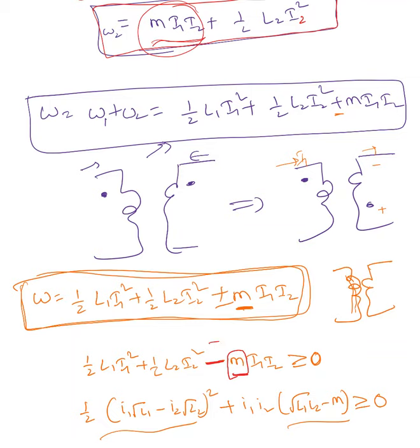Why didn't I choose plus? If I chose plus, when I take this to the other side, it will become minus M I1 I2. In reality, you don't have any negative M. That would indicate that it is acting like a generator which produces energy. An inductor is a passive element, it cannot produce any energy. So that's the reason, to find out the upper limit, I'm choosing this as a negative number.